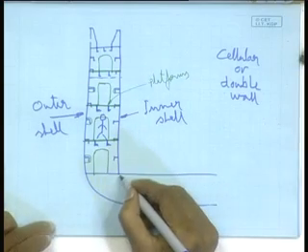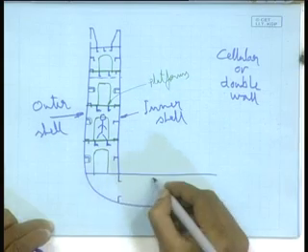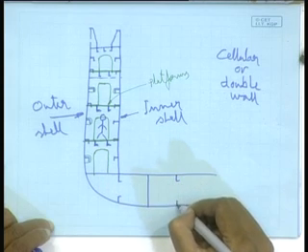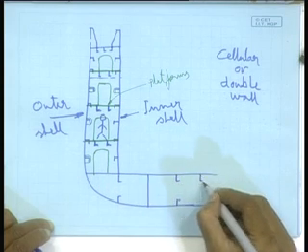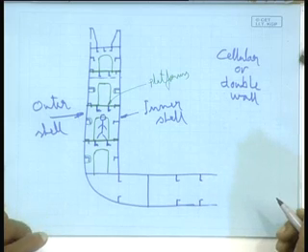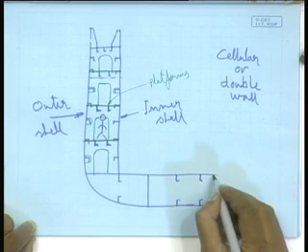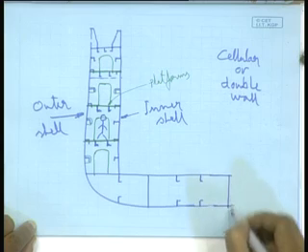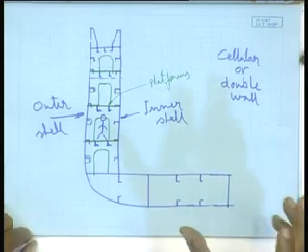So, this is what the double wall construction is. And now below this again the same thing, means the double bottom, there is no difference in the double bottom. Well, the only thing could be that one can decide upon a center girder or one can decide upon a duct keel.